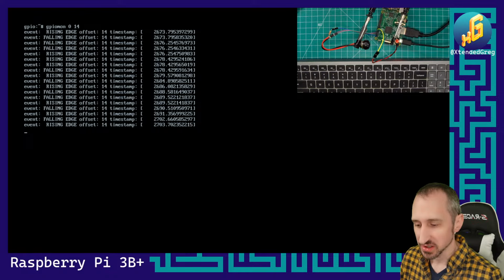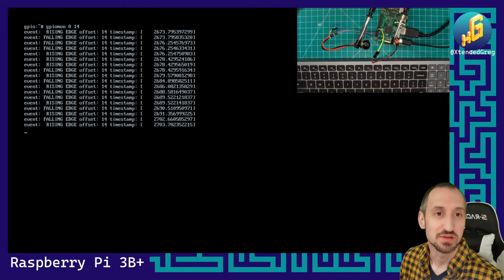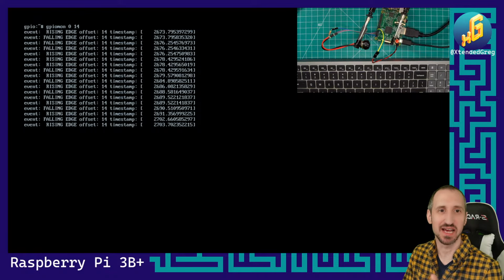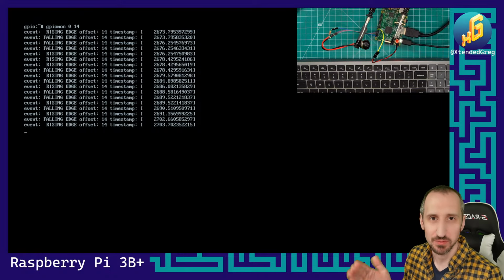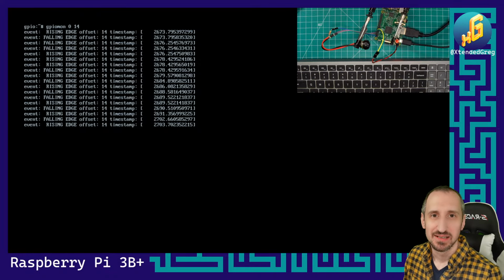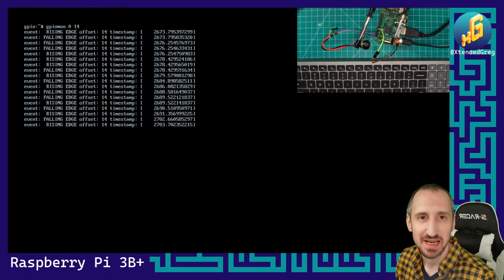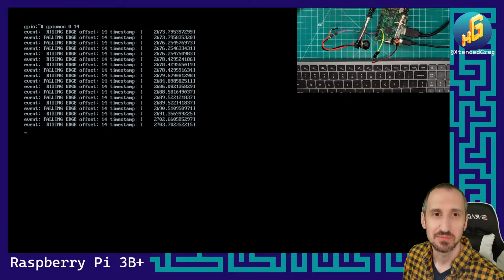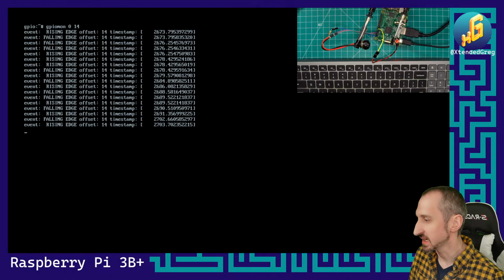But normally, the way that you would do it on a Raspberry Pi is you would add a little bit of delay in order to make sure that you're reading it only every so often. That way it kind of settles down, and hopefully you're reading it frequently enough to where they're pressing it for long enough for it to actually be detected. So that's something I would say about that.